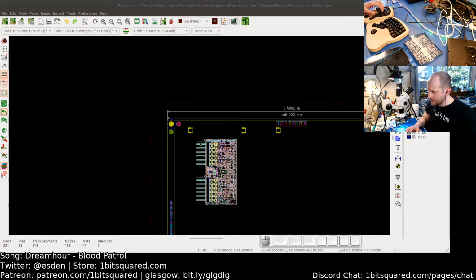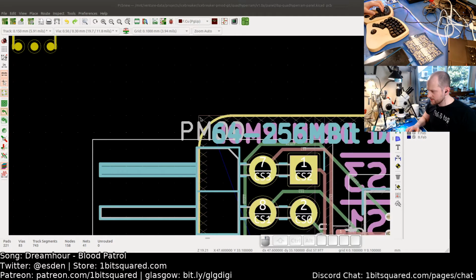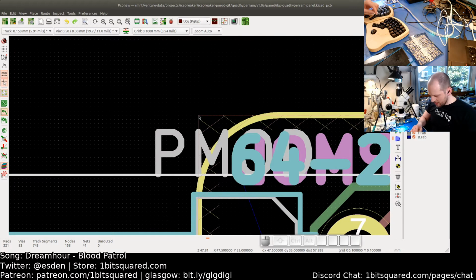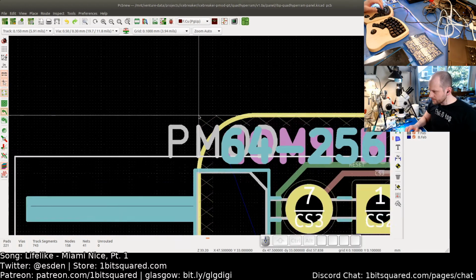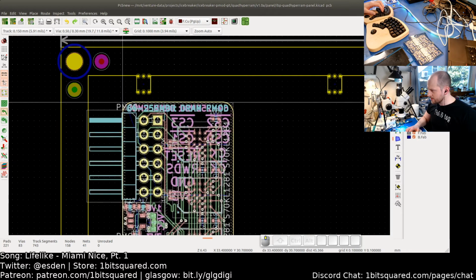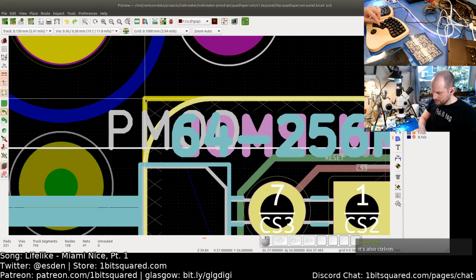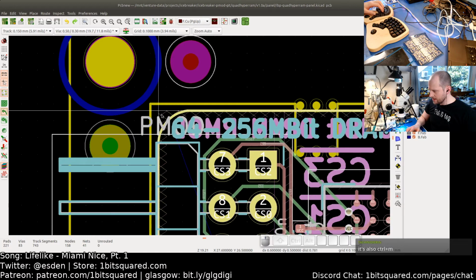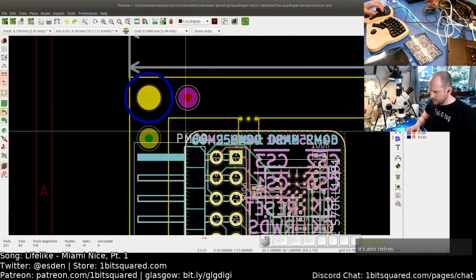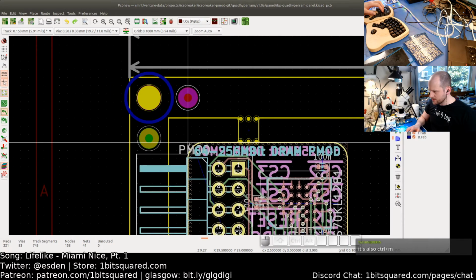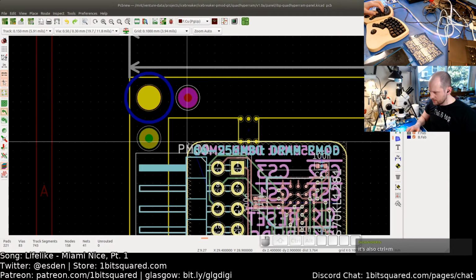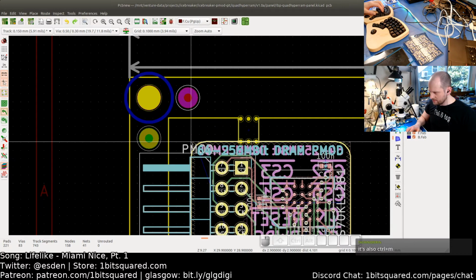The other way is to pick up a point. This is a more traditional way of doing this. Pick up a point, then it will anchor to the grid. Then I can go in here, press space, then the delta resets, or Control M, yes. And then I can move essentially 2 millimeters, 2.5 millimeters down, and 2.5 millimeters.